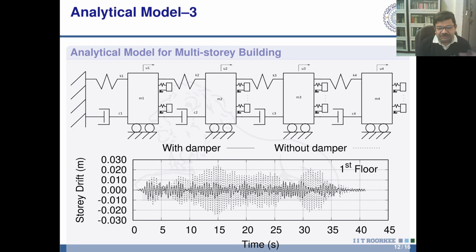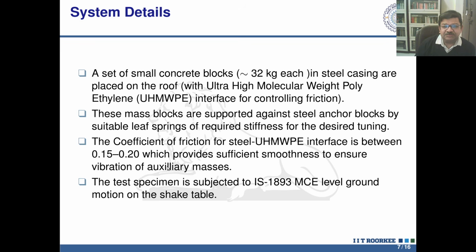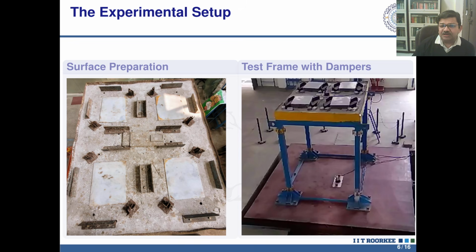So now, having done with the single degree of freedom system, we look at the possibility of what happens if we distribute these masses across several heights. We took a simple four-storied shear building model, with each floor housing these four oscillators. So essentially, we are looking at a system where we extend this particular system vertically. So just replicate this three more times.